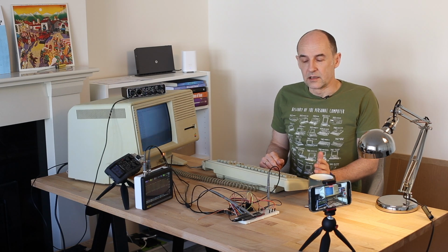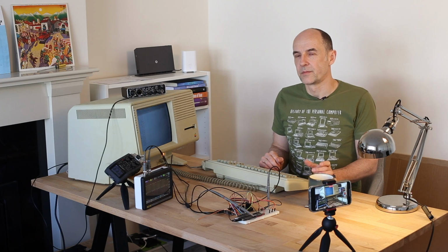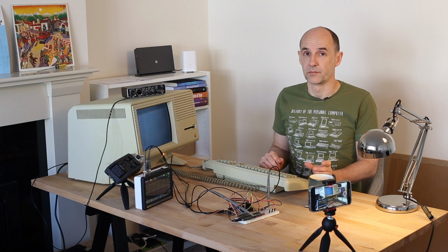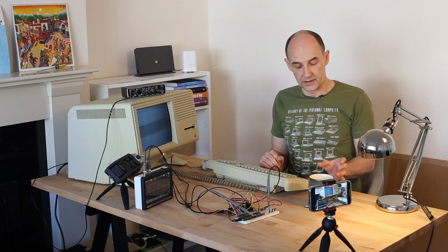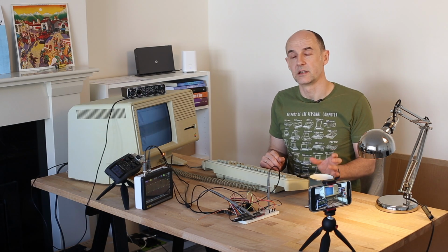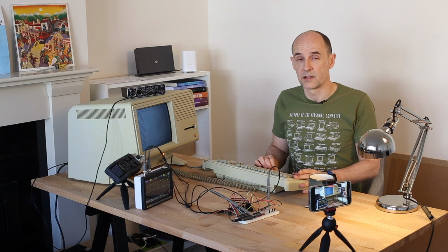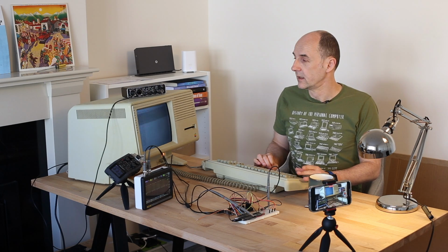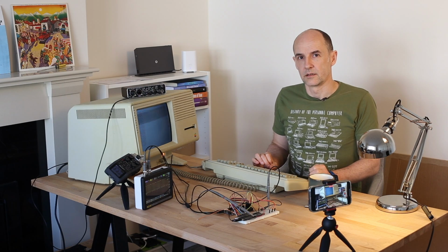But in Apple Lisa, it was not used to convert the digital representation of sound into analog sound; it was only used to convert the digital representation of volume level to the actual voltage level in the amplifier section. Let's look at the resistor ladder.